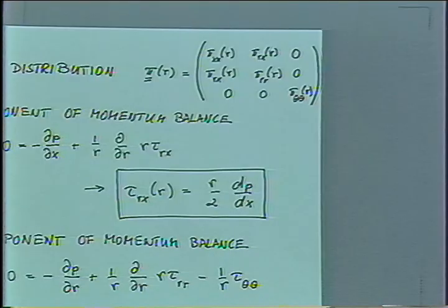Our question is about the boundary condition. In our model, which we used to get the kinematics in the system, we assumed symmetry at the center line. That means a finite stress there, or 0 shear rate in the center. And we also assumed a no-slip condition at the wall, so the velocity at the wall is equal to 0. Those boundary conditions enter when you take the momentum balance plus the material function and start integrating. You have to integrate twice, and that's where you enter the 2 boundary conditions to solve that flow problem.